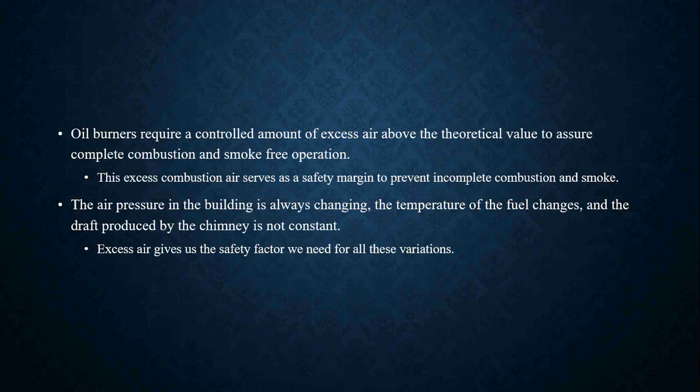Excess air, if you really think about that word, excess, it's leftover. It's additional. It's additional air that you are bringing in to help support the combustion process. If we deliver more than what we need, we can control how much is being delivered to our burner through our air shutters, our primary and our secondary air shutters.